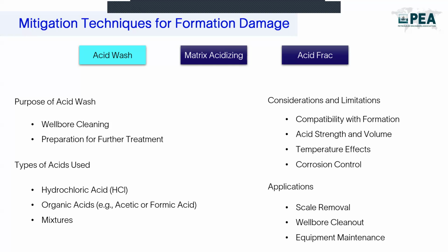The other consideration is the acid strength and the acid volume. The concentration and the volume of acid used must be carefully controlled to avoid over acidizing. This can lead to excessive corrosion or damage to the formation.